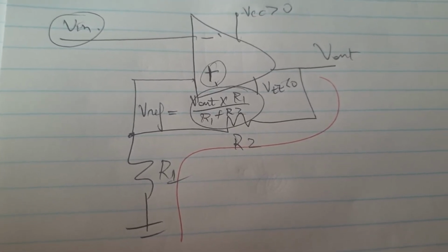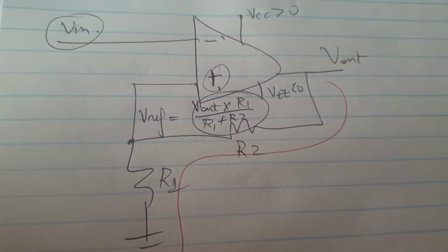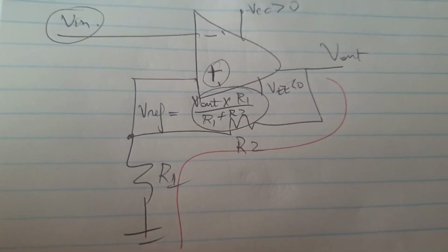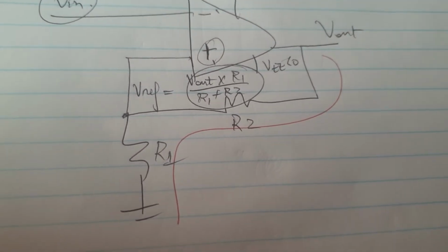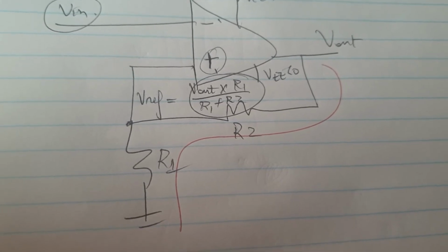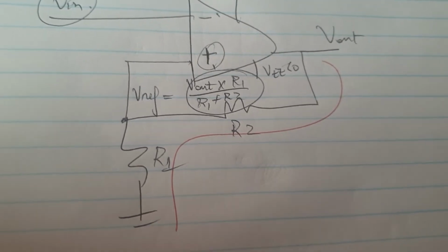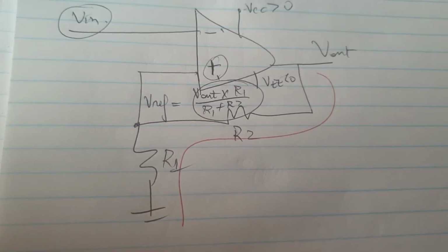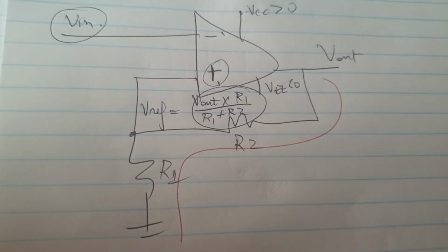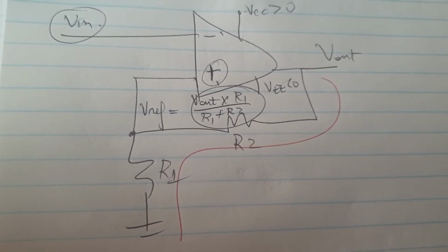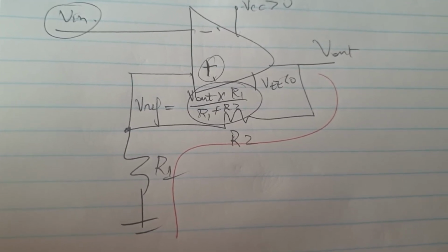So with that, the Schmitt trigger will eliminate that sensitivity. How so? Because of its feedback configuration. In other terms, the input tracks what is going on at the output. So somehow the output is dependent on the input behavior, and that maintains some level of reliability. There's some level of cooperation between the output and the input. But how does that technically happen? So we have a feedback resistor R2 and the input resistor R1 connected to set up the reference voltage.